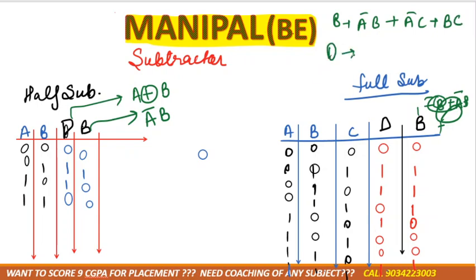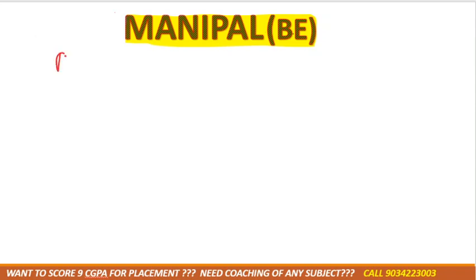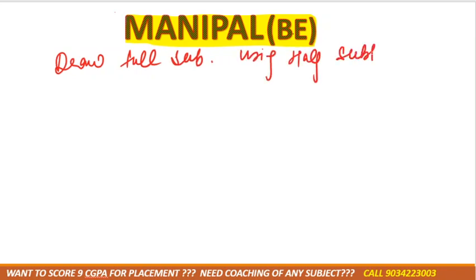Now the difference expression is A exor B exor C. Now again you need to draw that same thing, draw full subtractor using half subtractor.